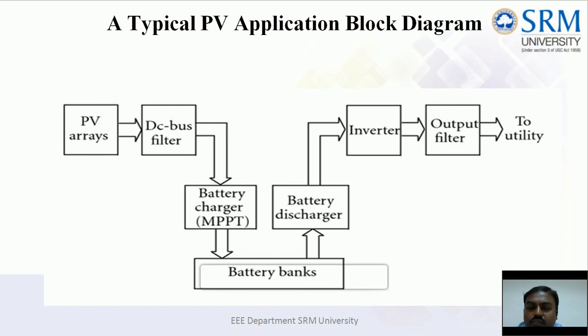You can also have standalone loads. When you want a closed loop operation of your standalone load, imagine an induction motor, you should also have a feedback from that closed loop given to the inverter pulses. So this is the bottom line of a PV application. Whatever projects you do, 90% of the components here are indispensable.